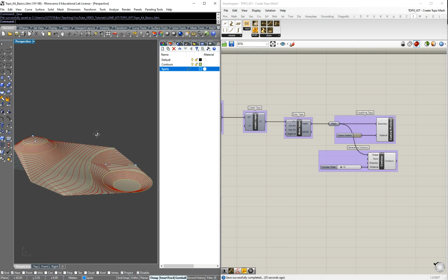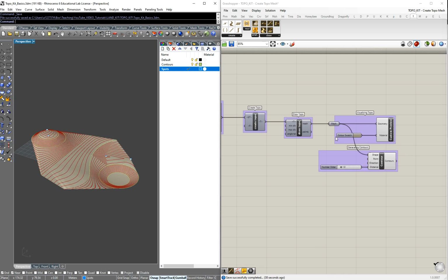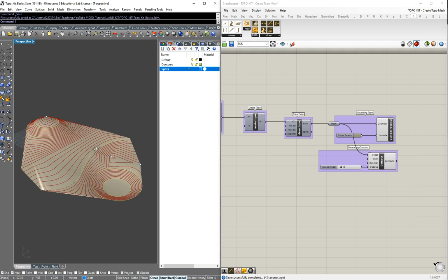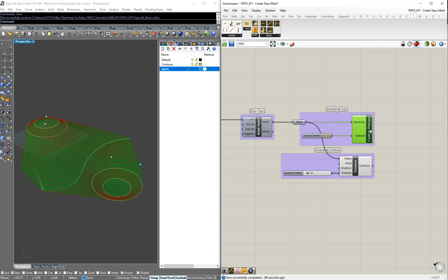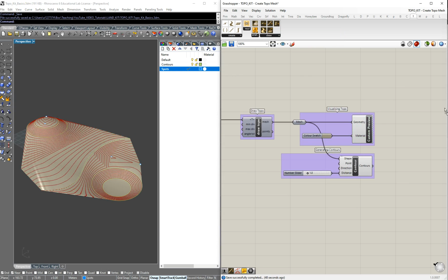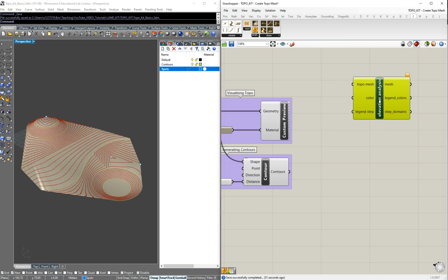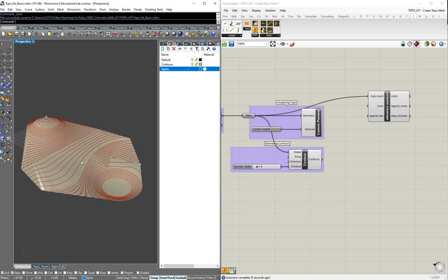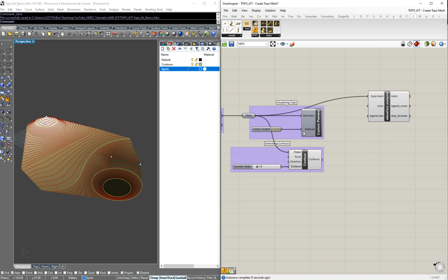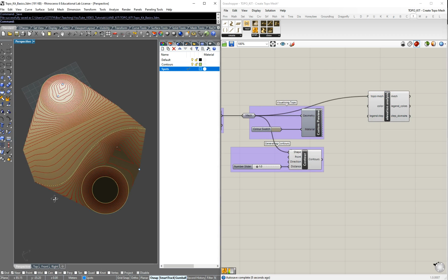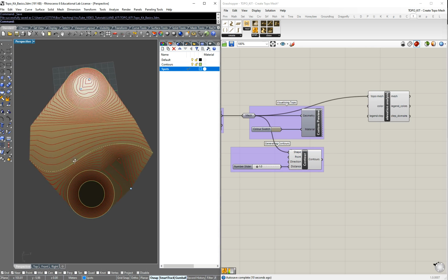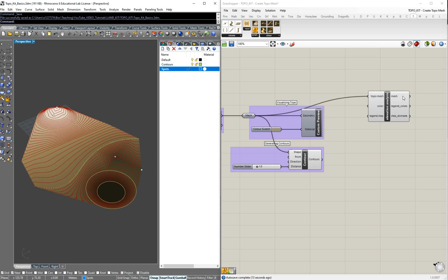One last thing I want to teach today is how you can do very basic analysis of this topography that you created. So with this on, we just add the elevation analysis, and here what we need to use is this mesh or the topo mesh. We can turn off this preview. As you can see, automatically the elevation is generated for you. And you can bake this mesh, or you can bake the legend colors. You can extract the domains.